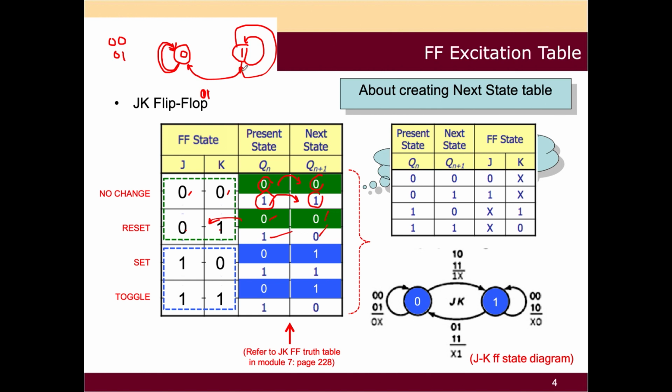There is no rule of clockwise or counterclockwise, as long as your arrow is from the state which is 1 to another state also 1. Either one is fine, but you also need to put your condition. So the condition over here is 0 0. Okay, hope that you understand. So refer to this state diagram because it's much more beautiful.